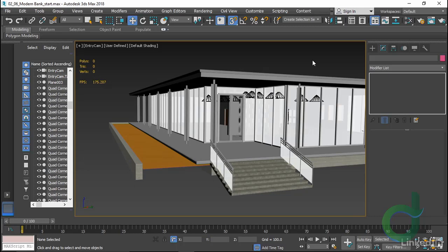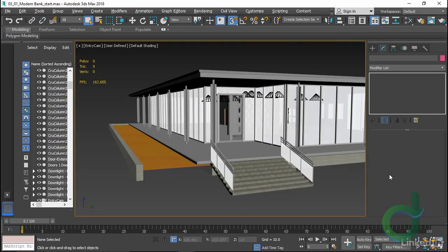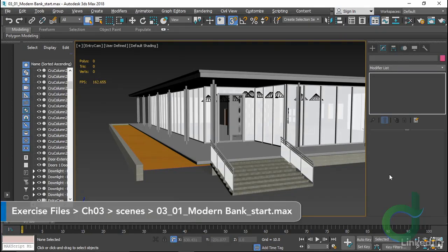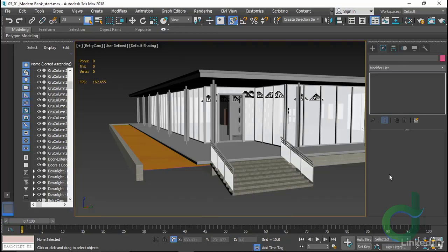It also depends on what you're doing with your model. Are you separating the BIM model from the pretty model, or the surface model we're going to run around in, either in a rendering or in VR? Assigning materials and where to assign them is an artistic choice. We're talking about the actual look of an object, not the material as in steel or stone or something else that Revit believes it to be made of, but in this case, what are these polygons covered on their surface with?